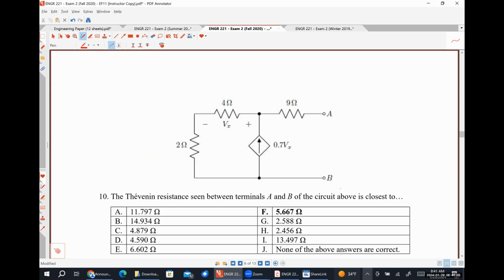Yes. So the test source method is used to find the equivalent resistance of a network. It can be done to find the equivalent resistance of any network, but we need to be looking at a dead network. This particular circuit only has a dependent source. It does not have any independent sources, so we literally can do nothing but apply the test source method. No other option works for us. So for this one, you want to use a voltage source or a current source? Voltage source.